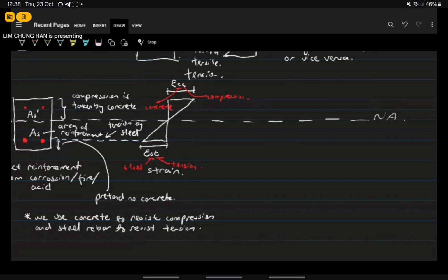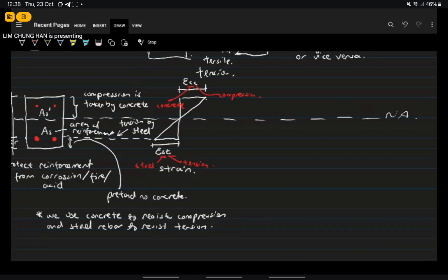Okay, now there is another one. Now, sometimes, as I said, we need to put reinforcement at the top as well, because the beam goes into tension at the top when it's a continuous beam. Also, sometimes when the beam is heavily loaded, even the concrete cannot take all the compression at the top. So we need to put compression steel sometimes. I will let you know later when.